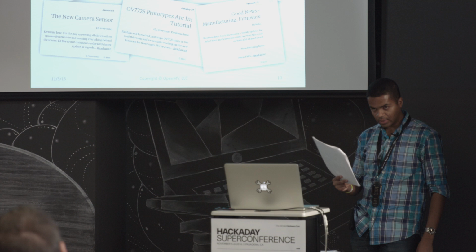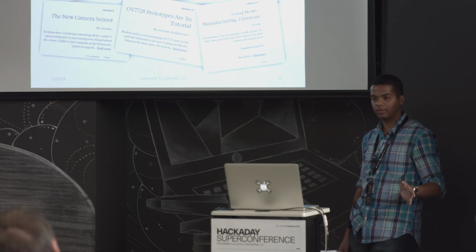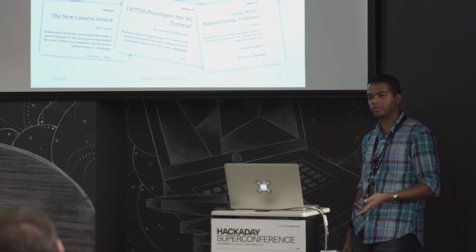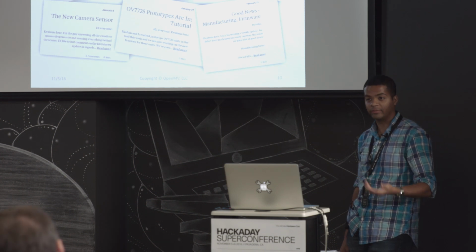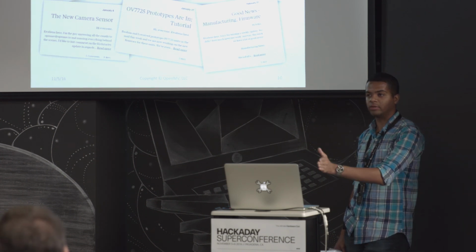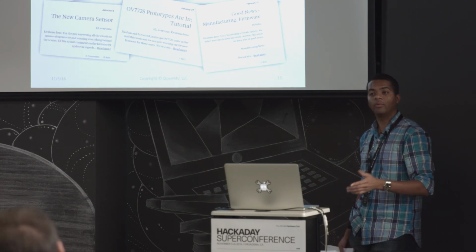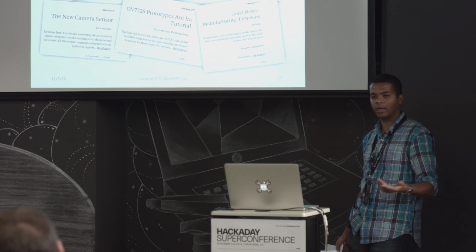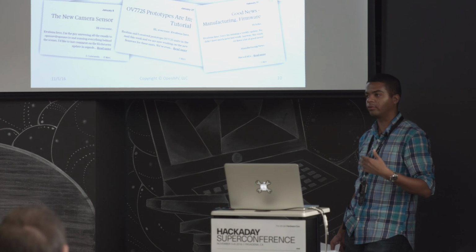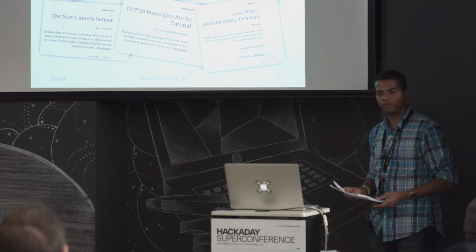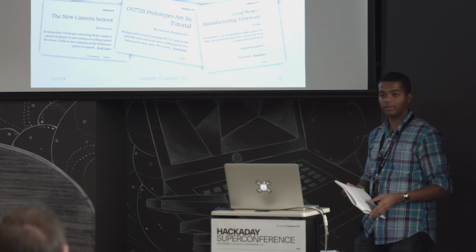And we also slowly tested manufacturing of 10 cameras to make sure that we could get it working with a new chip. In particular, we switched over to something called the OV7725. This is the image sensor that we bought directly from the factory, so we completely avoided all of the solder ball problems. And we did 10 at first, and they all worked. And then we did 40, 2 panels, to test to make sure they all worked. And again, we were successful. 40 out of 40 worked. So we were able to move forward, hit the button, and go into mass production and build all 1,500 new cams.